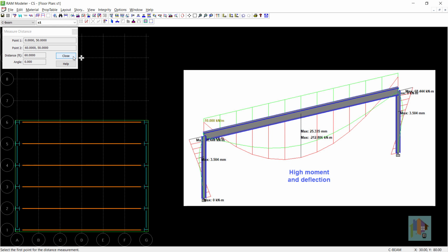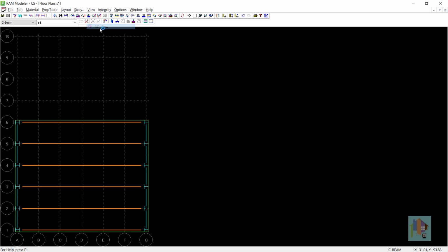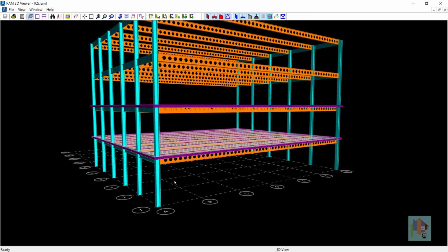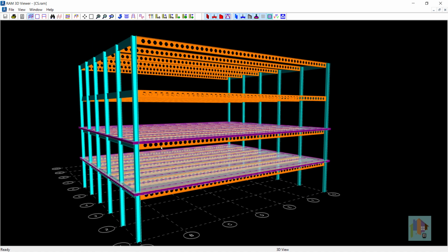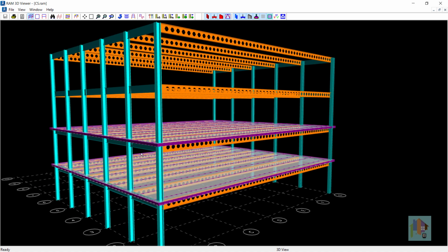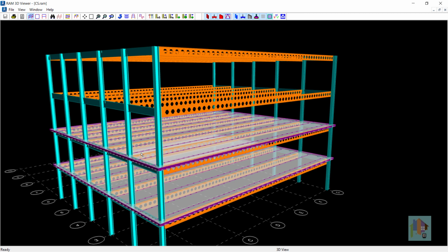If we use hot rolled section as a floor beam, then either we have to provide columns at intermediate level to reduce the deflection, or we have to use wide flange section with higher depth. In such case, if we use cellular beam in the transverse direction, these beams can easily reduce the deflection and also provide larger bending resistance. So we can remove the intermediate columns and provide cellular beam in the transverse direction along with wide flange section in the longitudinal direction. With this, we can reduce the cost in three aspects.